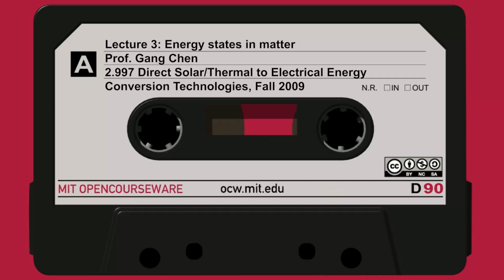One is atomic vibration, the lattice in the material. The atoms in the material vibrate and conduct heat. And the other is when charge itself carries heat, so it also conducts heat. So here we decompose this K into phonon and electron contributions. When you think about ZT, you look at those parameters: electrical conductivity, Seebeck coefficient, the phonon contribution to thermal conductivity, and the electron contribution to thermal conductivity.